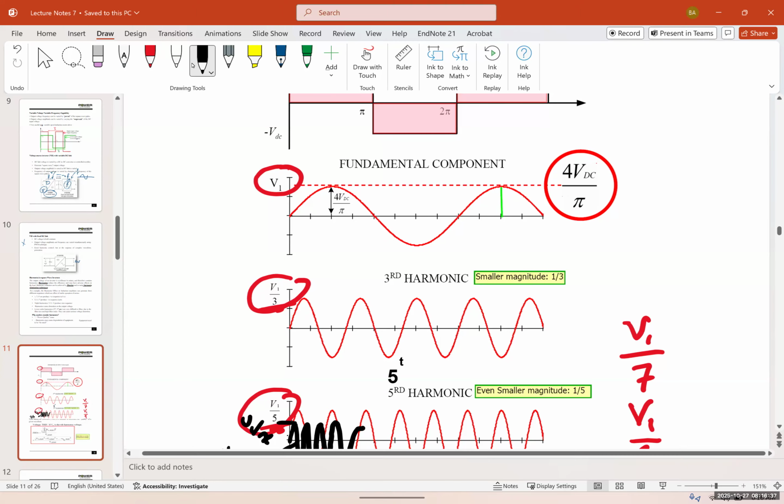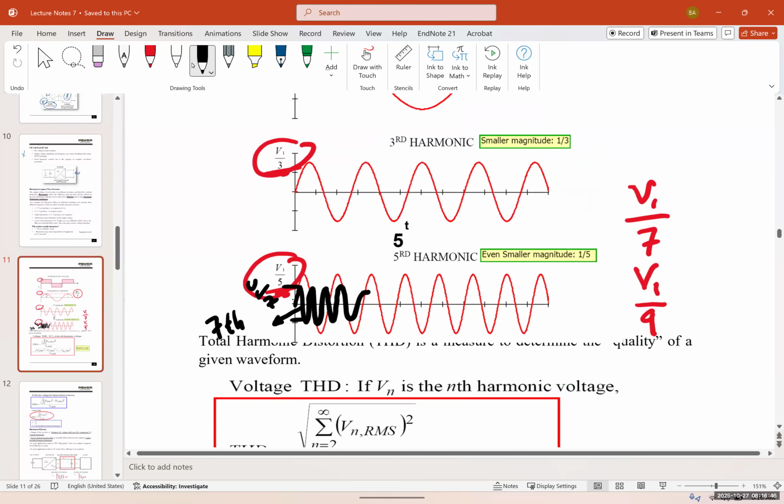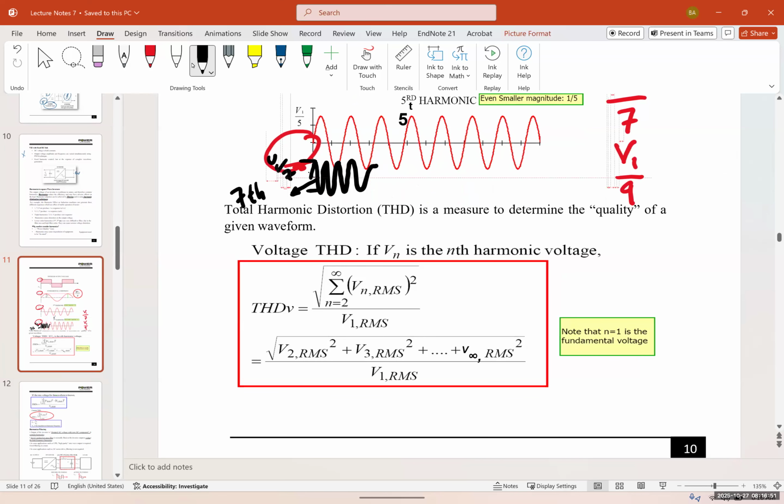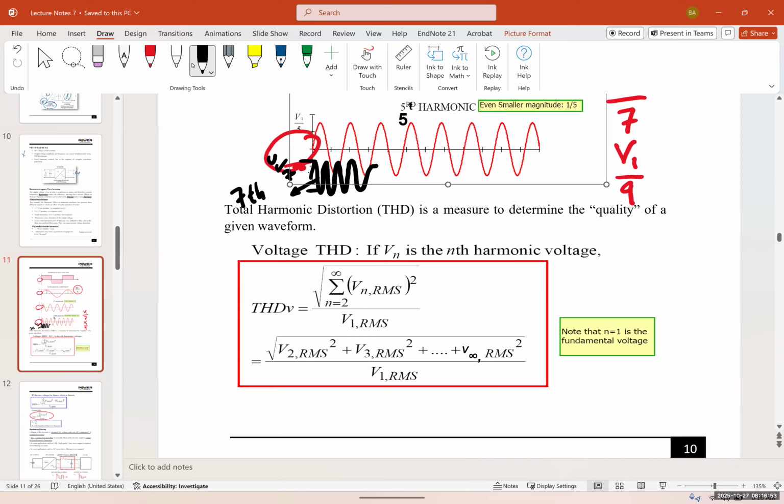But you have the fundamental, third, fifth. We are interested in the fundamental. The rest of it must be filtered out. Now, how can we filter this out? Using an RLC filter, but that causes a problem, and I will explain what problems and hurdles we have.